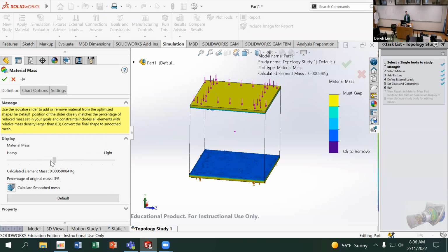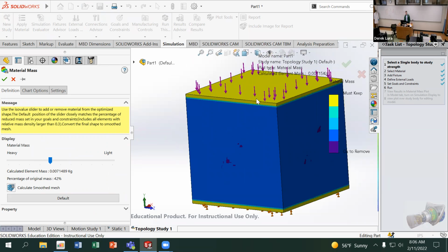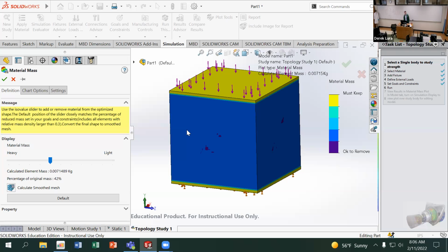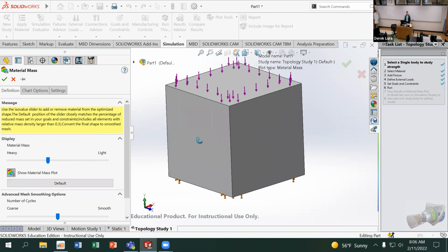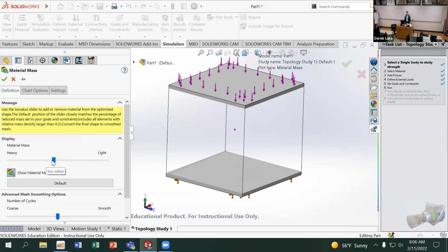So still not getting a good behavior because, again, of that very even stress distribution inside the part. You can see that the top and bottom wall, or floor and ceiling, is a little bit more realistic. I'm going to try smoothing the result around the middle here and see if we can get a little bit more of a pillar structure built up into this model. There are probably voids in here that we're not seeing at that point. Because again, it's trying to remove basically the entire middle section of the model at the same time, because all of those have the same stress value.